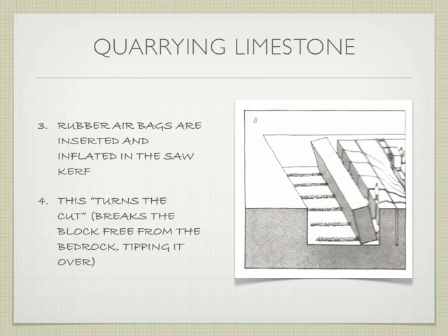Once they put the pillows in along that cut, they inflate the pillows with air, and that expansion causes the solid rock to crack right along where all those drill points are at the bottom. When that happens and it cracks, this big piece of limestone or granite or whatever type of stone it is falls over, and then they can start to work with that big chunk of stone.